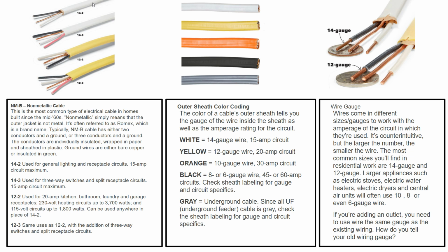That being said, that doesn't always work right. So we're trying to prevent fires, and we're trying to prevent injury. So black wire, white wire. Okay, 2 wires. That's 14-2. 14-3, there are 4 wires. One's the ground, 3 conductors.